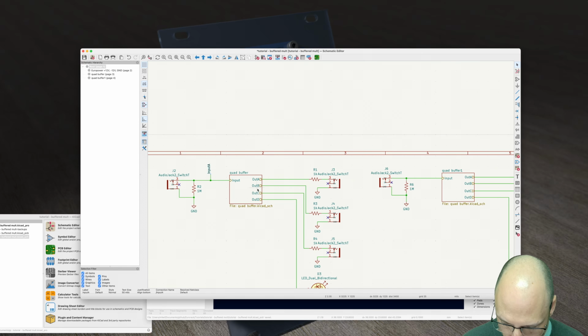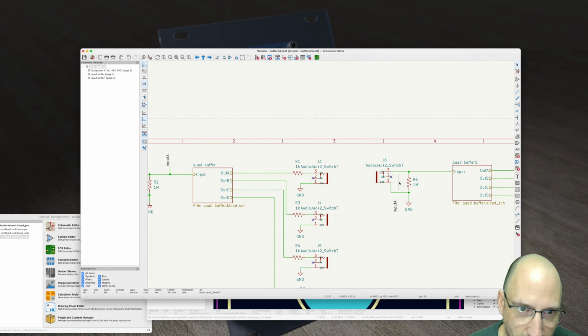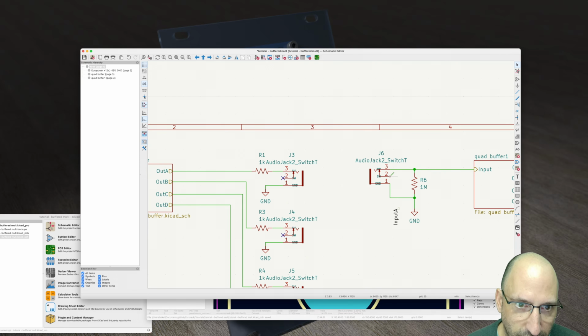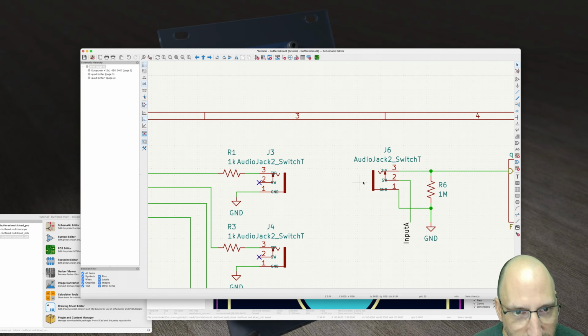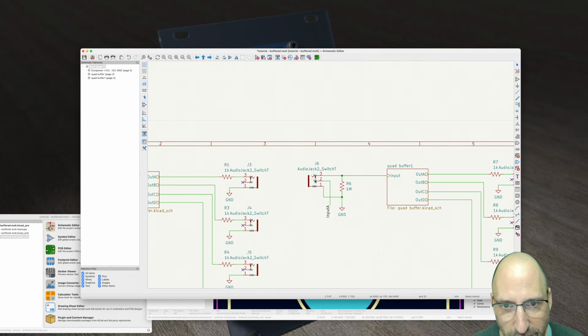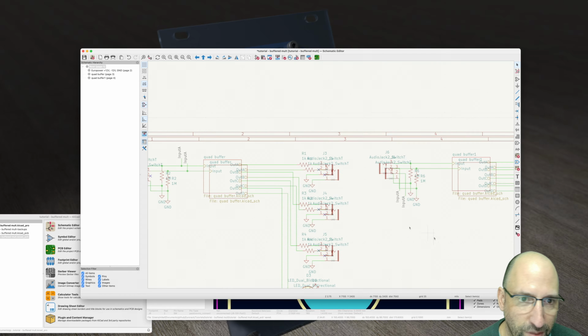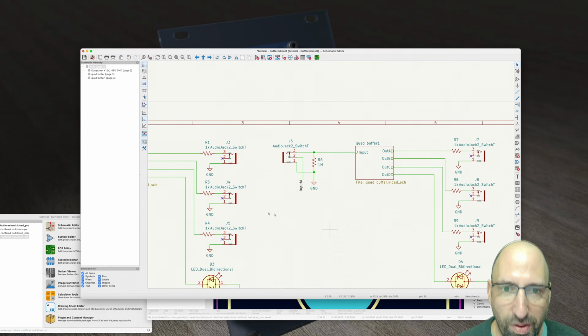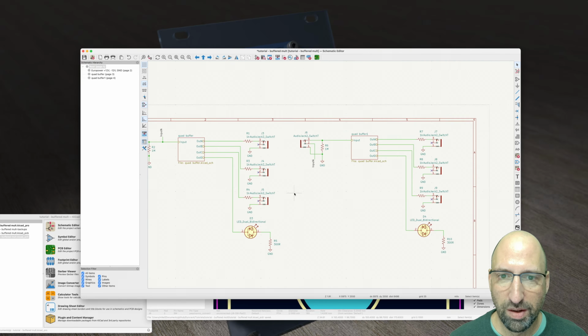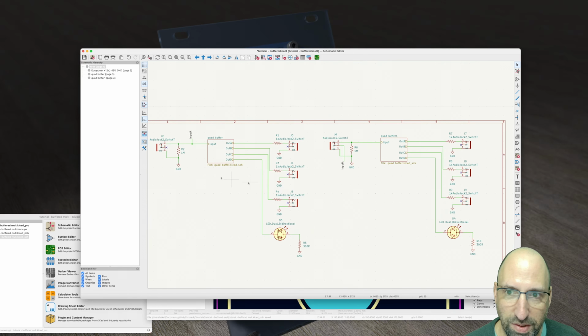And we want that input to go into the switch so that the switch contact is broken when you push a jack into this, and then it's going from the jack's tip into the circuit. Otherwise, if there's no jack in here, it's going to get a duplicate of the input from input A and buffer it. So that would be pretty awesome. Quite a neat little change without adding any more components.